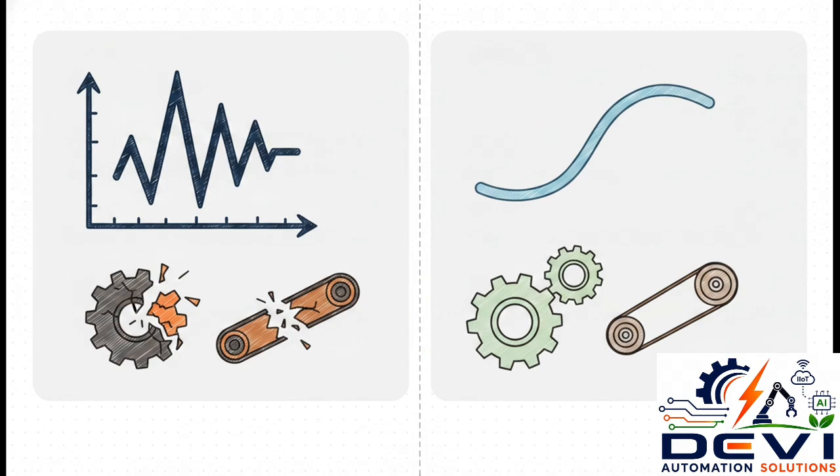But by dialing in the acceleration and deceleration time parameters on a VFD, we get a beautifully smooth soft start and soft stop. The motor ramps up and ramps down perfectly. Honestly, this alone extends the life of your pumps, conveyors, and fans by years.